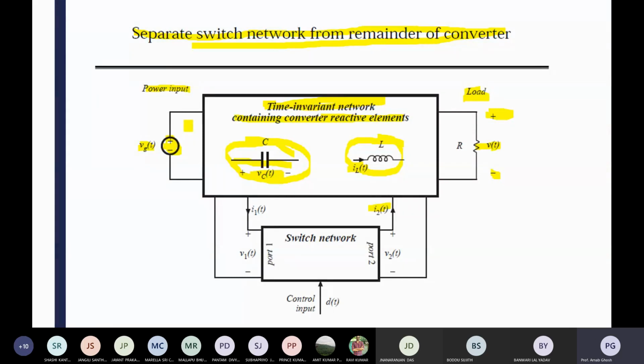Comparing them, after some time you are also using some controller. The time constant of the controller in current mode control should be comparatively high, or rather, the response time should be at least 5 times that of the controller in your voltage loop.